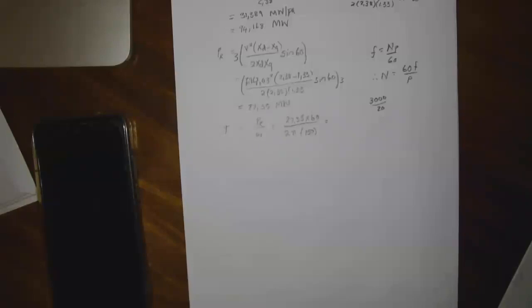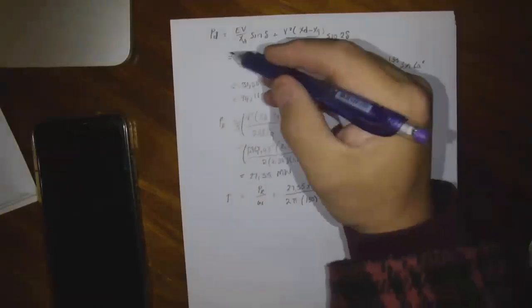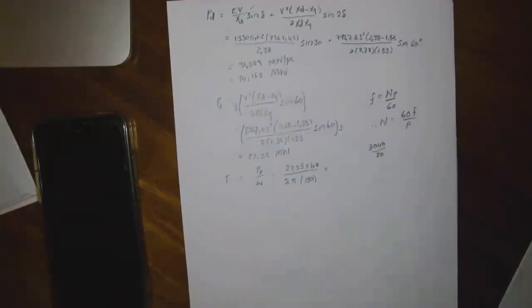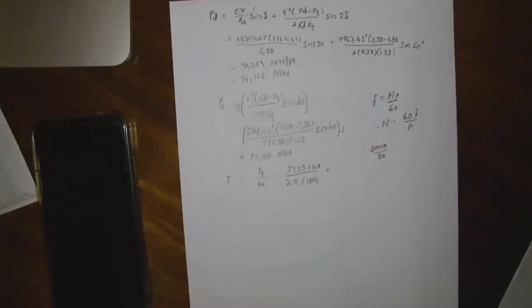In relation to that, can I ask something? When you say that once the excitation has been switched off, we should calculate the developed power, does that mean that the excitation part of my formula I remove, and then I just calculate developed power in terms of reluctance? Yeah. So don't talk about developed power anymore, now it's reluctance power.